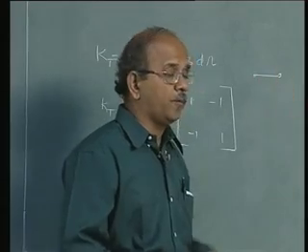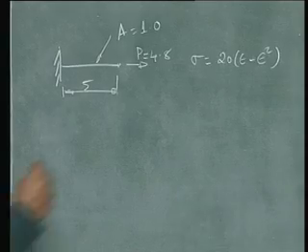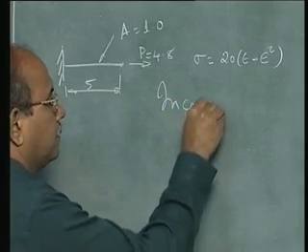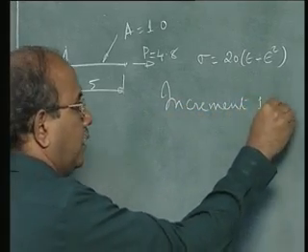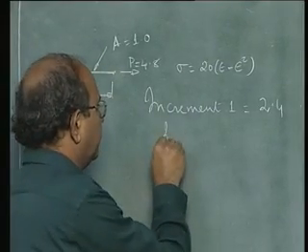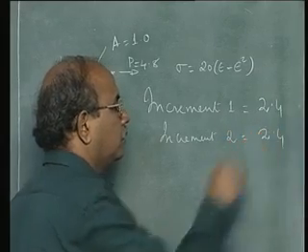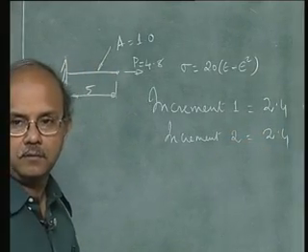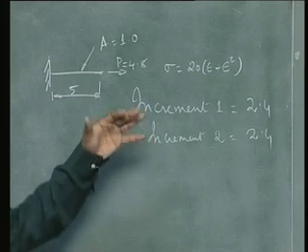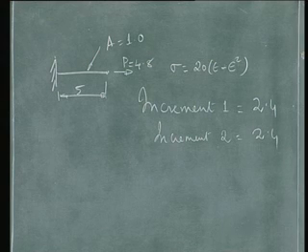And apply the load 4.8 in 2 increments. In other words, in increment 1, apply a load of 2.4, and in increment 2, apply a load of 2.4, further to the first 2.4. That means that the total load is equal to 4.8.